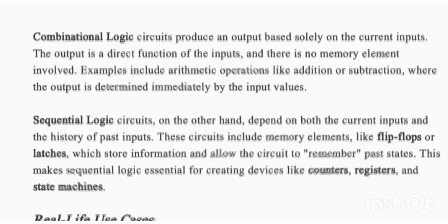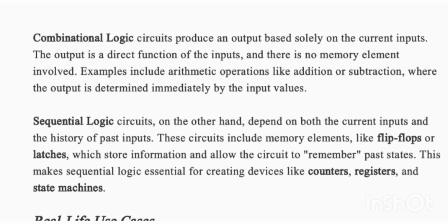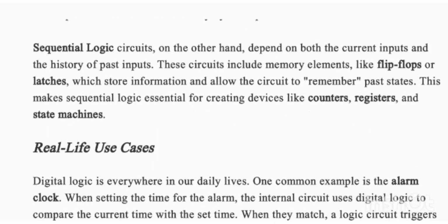Sequential logic circuits, on the other hand, depend on both the current inputs and the history of past inputs. These circuits include memory elements like flip-flops or latches, which store information and allow the circuit to remember past states. This makes sequential logic essential for creating devices like counters, registers, and state machines.